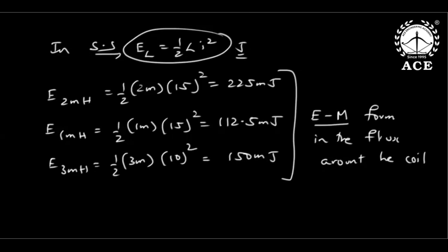Okay, sir. Your argument, I understood, is valid when there is actually a time variance. But here we are considering that all those are over and it has reached a steady state. In steady state, this current is constant and the rate of change of current is 0. So whatever energy it has stored, it would have stored in the transient state when changes occurred. Then it is retaining this energy in steady state. That is how the energy stored up to infinity is the energy at infinity for the inductor. Okay, sir. That concept tomorrow, we will get an excellent example tomorrow.